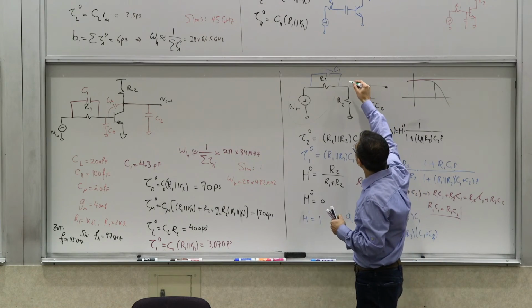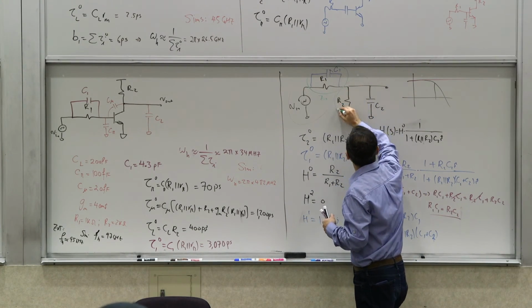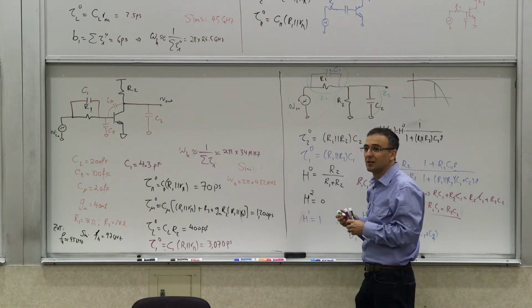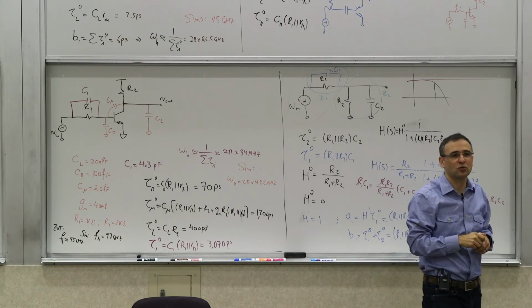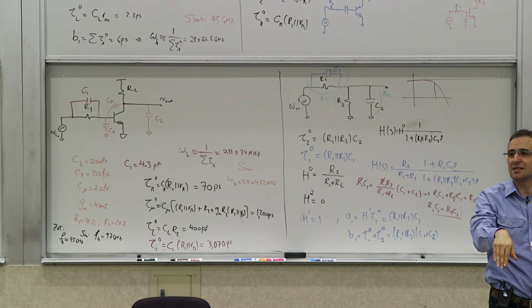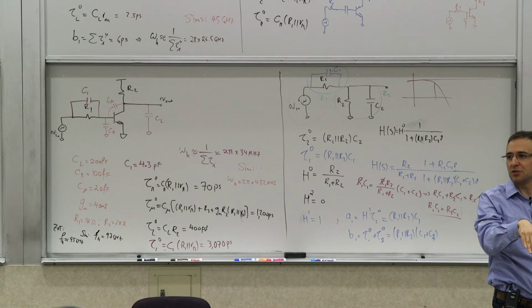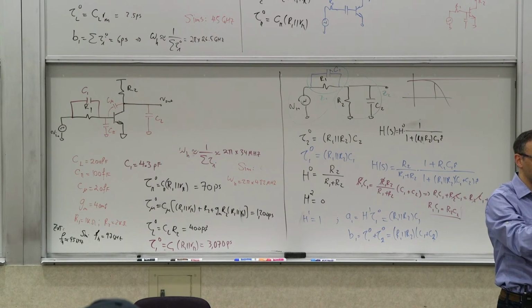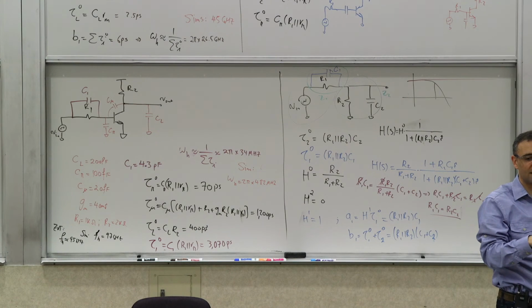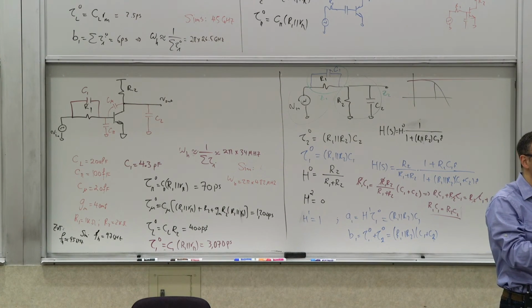But think about this as an impedance, Z1, and this as an impedance, Z2. If I choose Z1 and Z2 so that they scale the same way with frequency, if they both drop with frequency at the same rate, the ratio which will determine the division, the voltage division ratio, is Z2 over Z1 plus Z2.